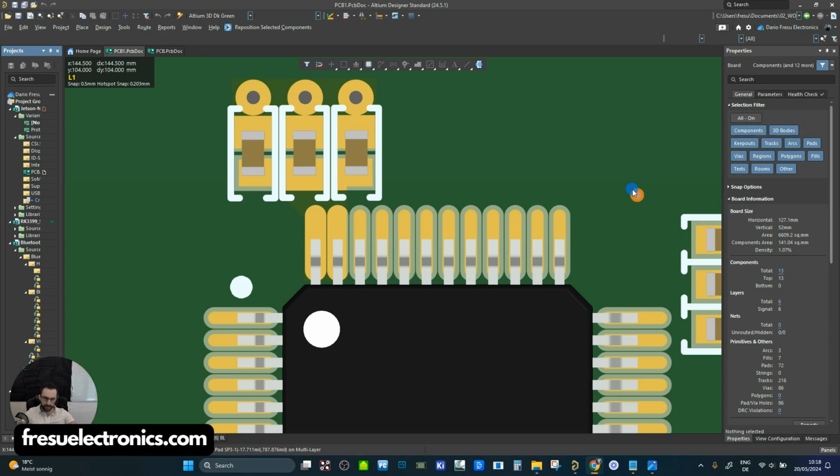So before we proceed, we actually have to start to demystify some of the concepts that we have about decoupling capacitors, because these are widespread within the PCB community. So we need to really take a look at those. One of the concepts that is quite widespread is that we can choose different values of capacitance to improve the power delivery network. And this is not necessarily true.